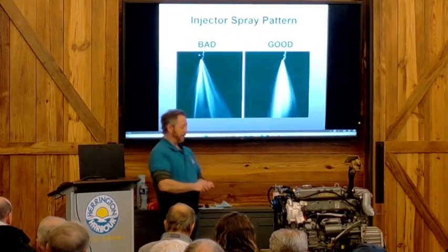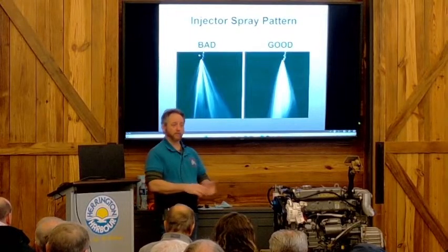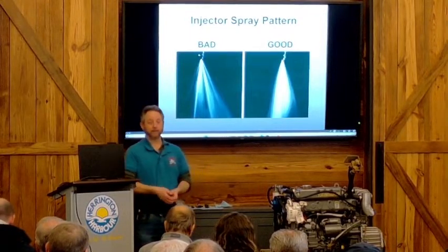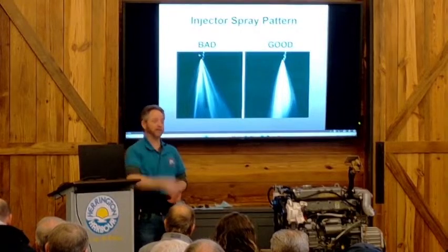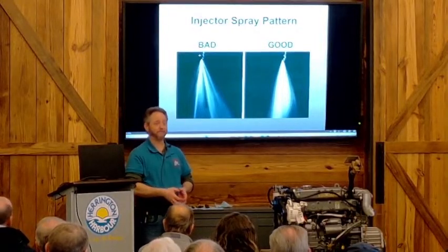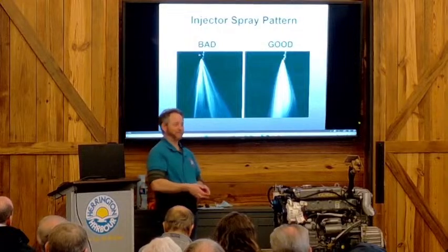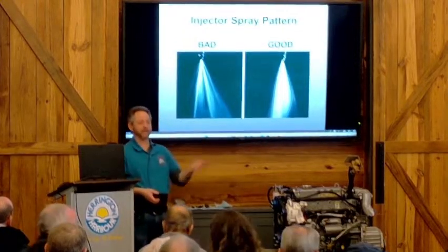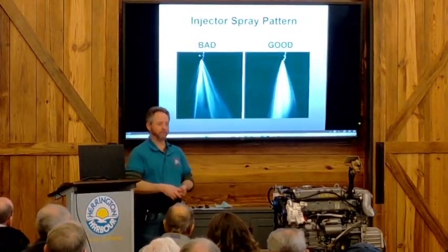When you start talking about the cost, it's getting the injectors out and putting them back in. Some engines they pop right on out, and some engines it's not fun. I've had to pull cylinder heads off in order to get injectors out before because they get rusted in place.